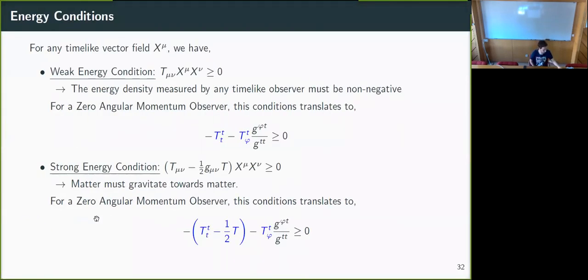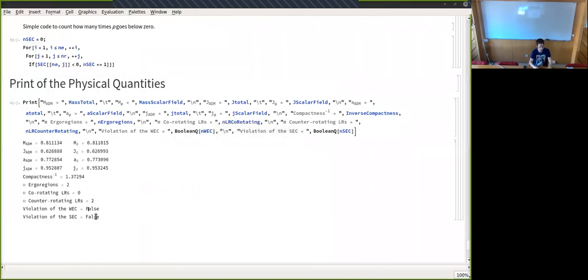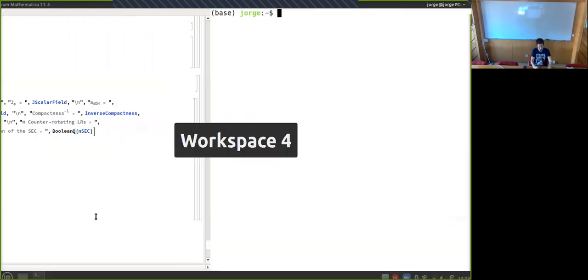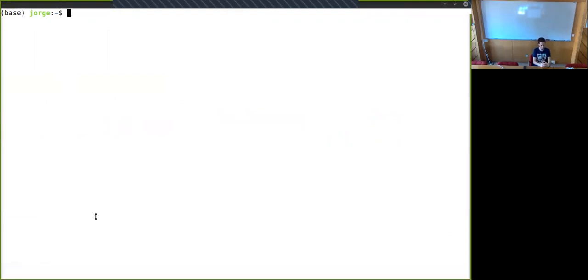But now, since I didn't mention it before, and since I still have a bit of time, I can show you. This was only for one solution, but you may want to have all the solutions in the domain of existence. Since the solver uses a Newton-Raphson method, you always have to provide an initial guess. But this initial guess is normally just a challenge in the beginning, because as soon as you have the first solution, you can always use that one to obtain the next one.